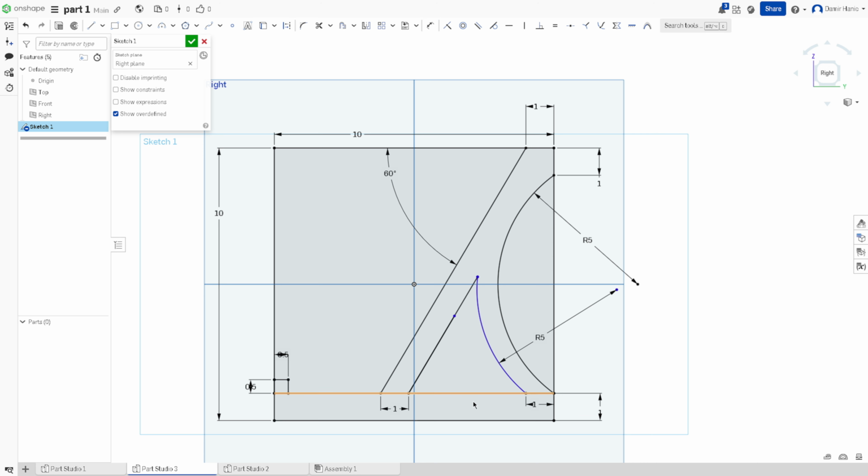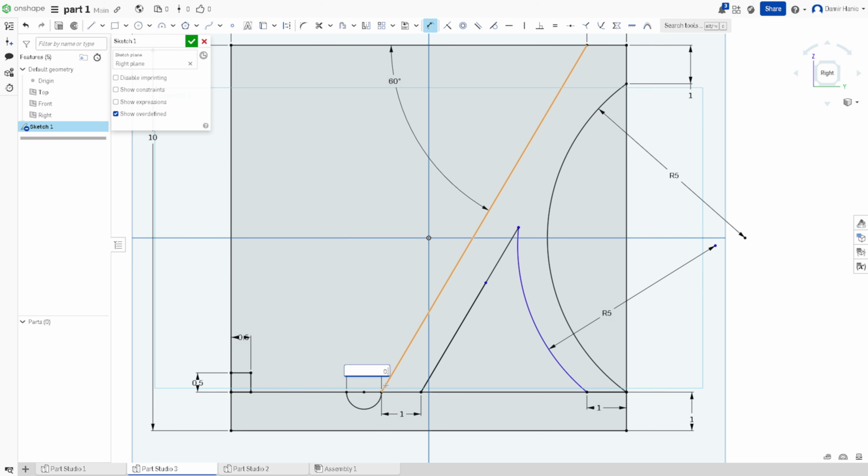Now what we are missing is something over here. So that means that we're gonna create a 3-point arc circle, but we're gonna use this to actually create a hole where the phone is gonna enter and not slip up. So I think the half centimeter is kinda okay, maybe 1 centimeter. I think this is gonna be more representative. And now we use some, let's see, advanced tool, which is called a pattern. You have linear pattern, circular pattern, or transform, and we can use linear pattern, select what we want, and we can move it to the value we want, and we're gonna get something like this.